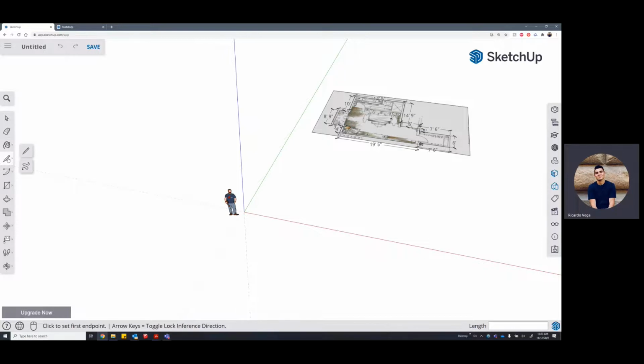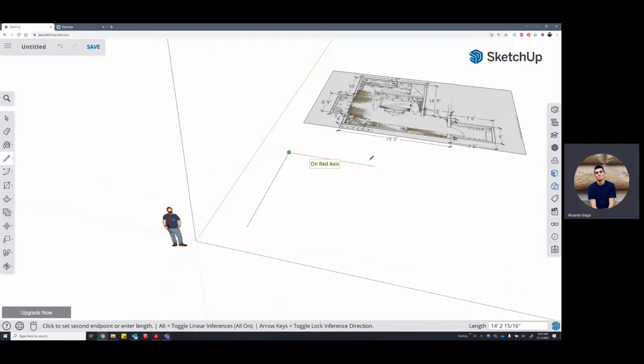We have our line tool, and basically what we want to use is a line pencil to create straight lines. And the way that this works is you select your first point and then your second point to finish the line. So you click on your first point, and then you click on your second point, and that finishes the line. Usually it'll want to continue doing more lines, but you can hit spacebar to end it. So if I hit spacebar, it ends the command. Let's get into the line work a little bit more.